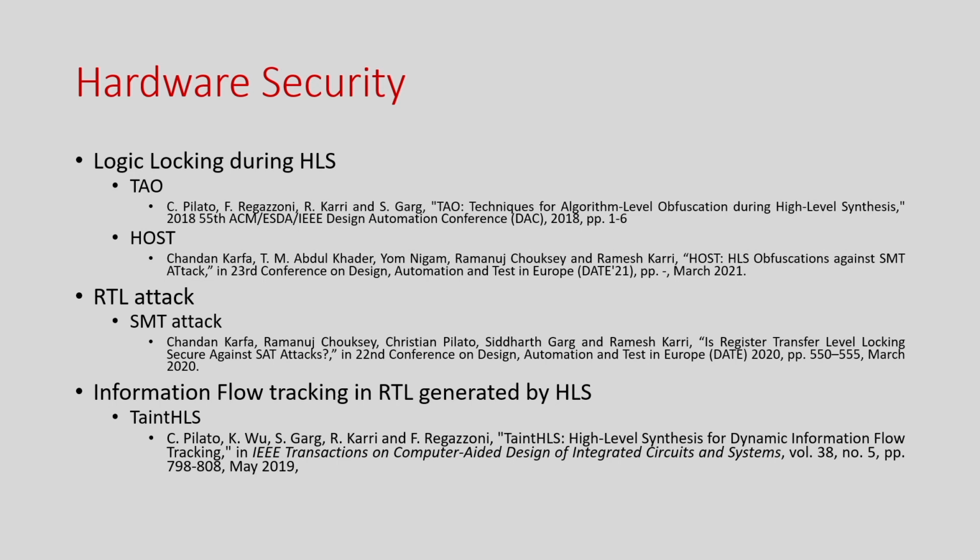In this course we have also discussed that logic locking is nothing but adding some extra key in the circuit and giving that locked circuit to a third party, but not giving the key. When you ship the whole IC, you just store that particular key in a non-volatile memory and give that functional IP to the customer. Since the correct key is already there in the functional IP, it will give the correct output. But the locked circuit which the untrusted employee or untrusted component accesses does not have the key, so he cannot use it.